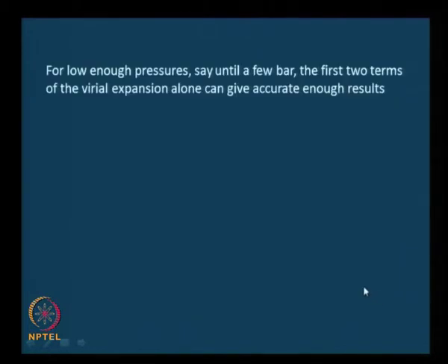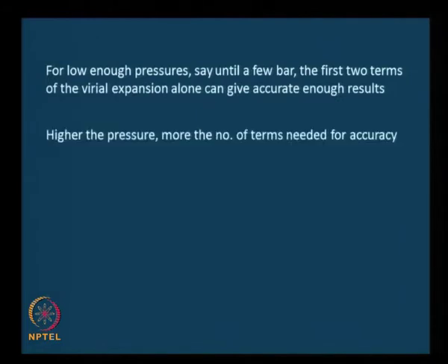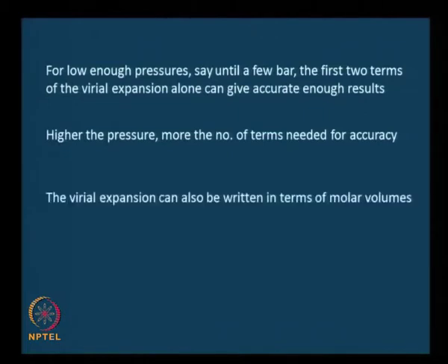And also for low enough pressures, say about a few bar, just the first two or three terms of the Virial expansion is good enough to give an acceptably accurate representation of the gas behavior. But higher the pressure, more terms are needed to accurately represent the behavior.